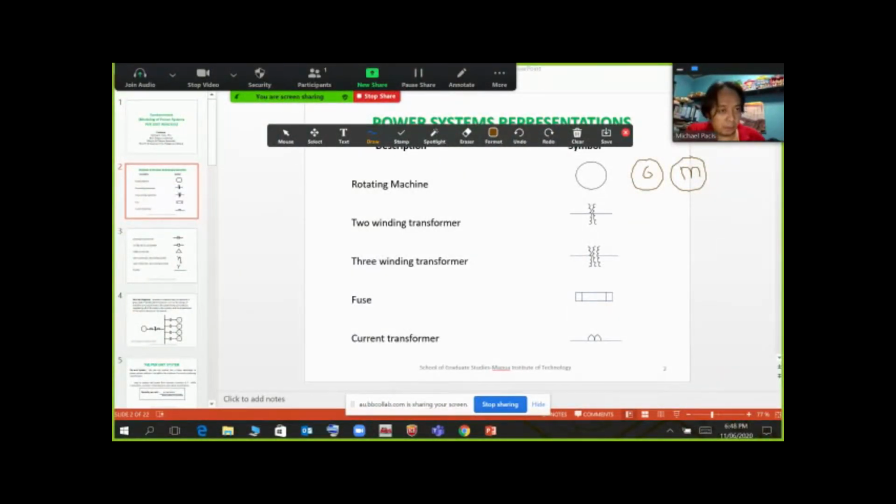So for a two-winding transformer, we have a coil, a single phase, two-wire system. However, if we have connections like this, Y to delta, delta to Y ground, Y ground, you're considering the system as a three-phase, three-wire system. So it means we can simplify things instead of having three coils connected between lines.